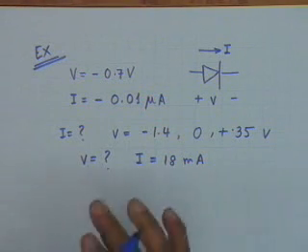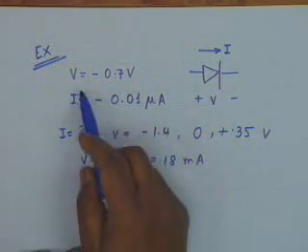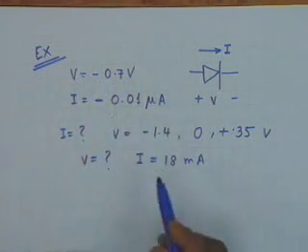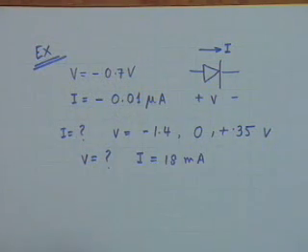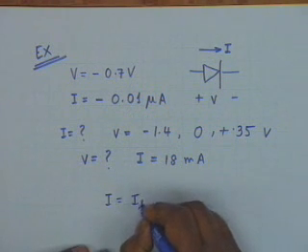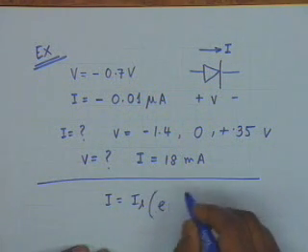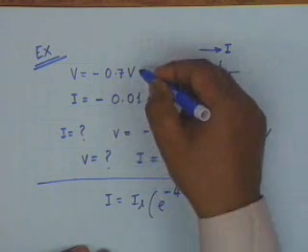Basically it is an interplay of the same equation. However, there are some simplifying features which I wish you to notice. Firstly, at a voltage of minus 0.7, capital I is minus 0.01 microampere. Now, if you substitute in this equation I equal to Is (e to the power minus 40 times 0.7, minus 1), why minus?